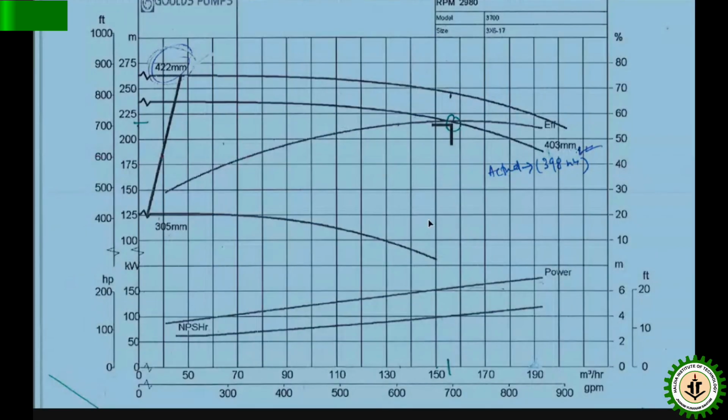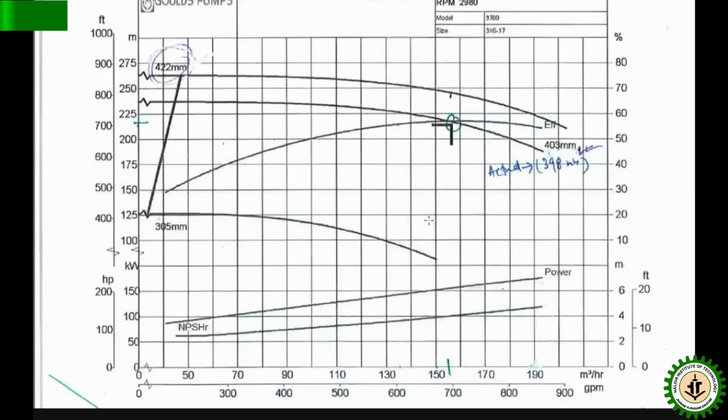Impeller size up or impeller trimming, in any case, as I showed you, follows affinity curve concepts. By the affinity laws, you can understand how much the flow requirement would be, and how much the change in pressure and power would be. For power it is cubic, for pressure it is square, but for flow it is directly proportional to the speed or the diameter of the impeller. Similarly, you can vary the speed, keeping diameter fixed, and that case also follows this concept.